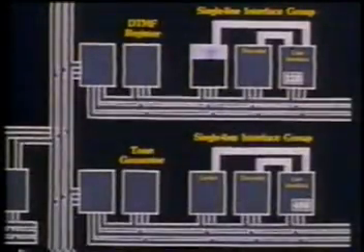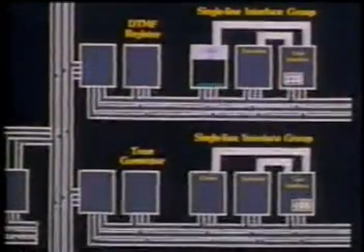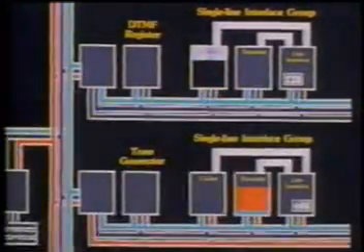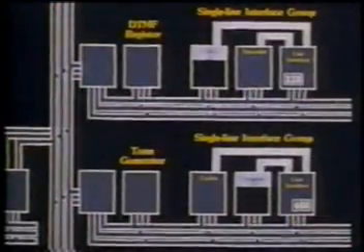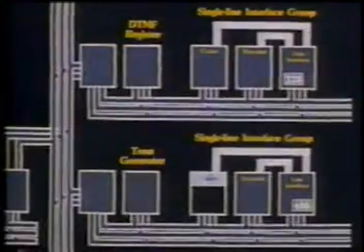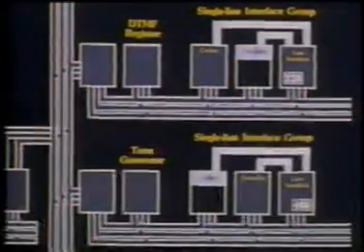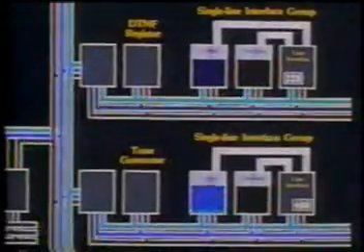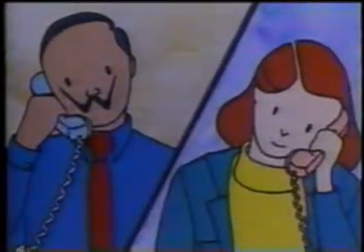At Dave's coder, his analog signal is sampled and coded into a 12-bit PCM word. Upon a transmit command, it is placed upon the parallel digital bus, and in the next time slot is received by Kathy's decoder and decoded back into the analog sample. In the same frame period, her analog signal is sampled, coded, switched, and decoded at his interface group. And with the high speed of time division multiplexing, these PCM words are transmitted and received 12,000 times a second. In this way, Dave and Kathy are able to converse.